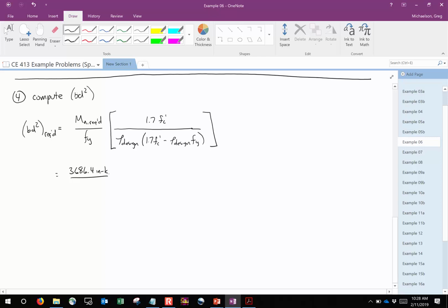Now, Fy. Fy is what? 60 ksi. Now, before I move on, see why I went ahead and had you all convert the moments into inch-kips? Because we have kips per square inch. So a lot of times in design mode, it makes sense to have your moments in inch-kips because you can easily compute your stresses in ksi and all the units work out. All right. Now, what I'm going to do is use braces here. This is going to be a real big fraction.